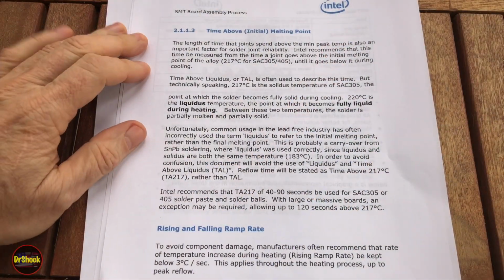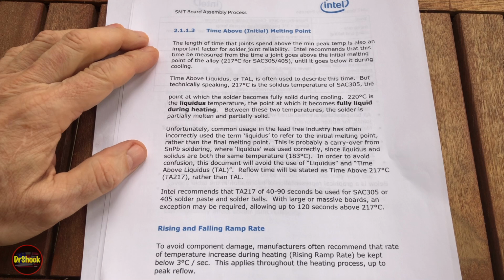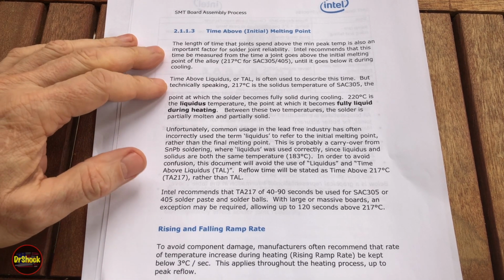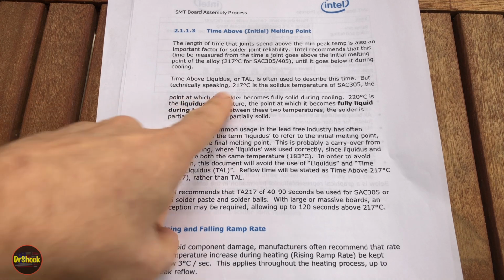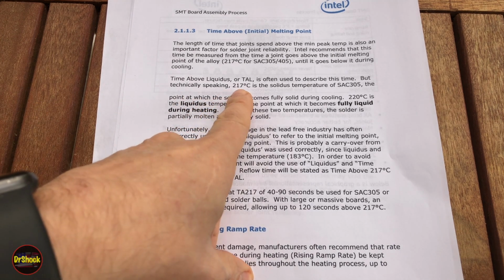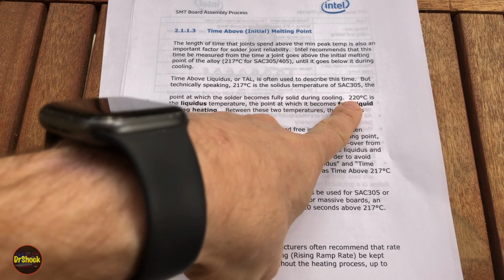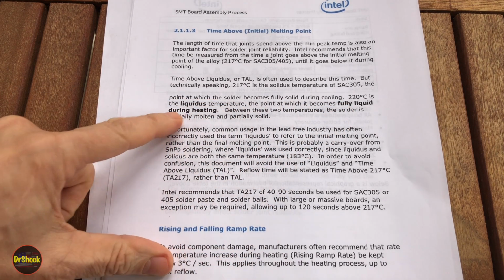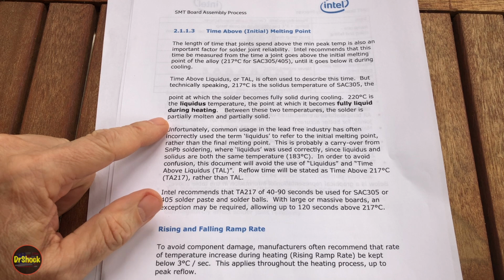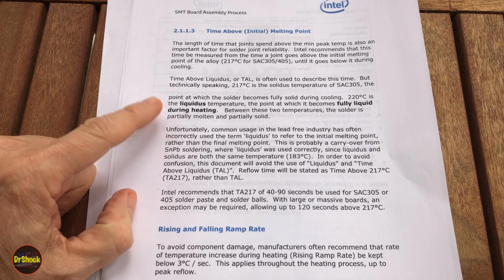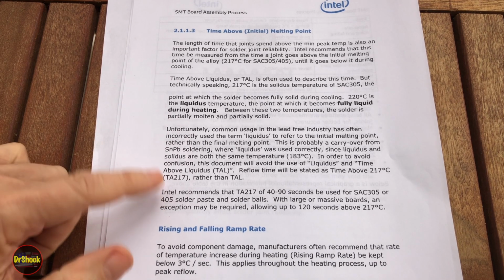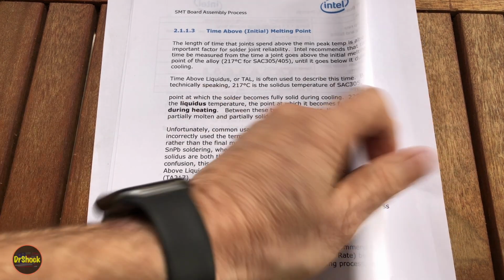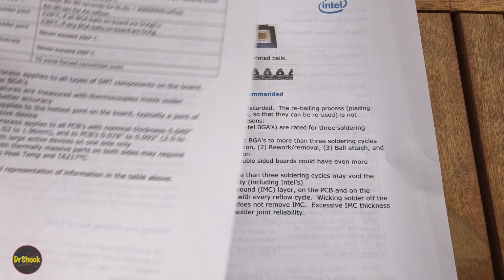All right, guys, using the manufacturer's data sheets, and this is really common to everything. There's really nothing unique about this, but just as an illustration, we're going to need to get this up to 217 degrees and then right at 220 degrees Celsius. That's the temperature at which this non-leaded solder that was used in these days would be fully liquid during heating. So that's the target that we're going to want. And they'll talk to you about a reflow profile, and I'll show you that as well. There's some pages in here on that as well.